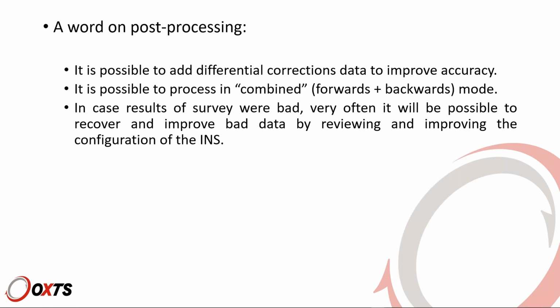Just a word on post-processing. Like I mentioned, if you are not only interested in real-time data, then post-processing can be a very good option. It has a few advantages. One, you can add differential corrections. Two, you can process in combined mode. I'll show you an example in a second. So that's forwards and backwards, and not just in simulated mode, similar to real time. And also you can tweak your configuration.